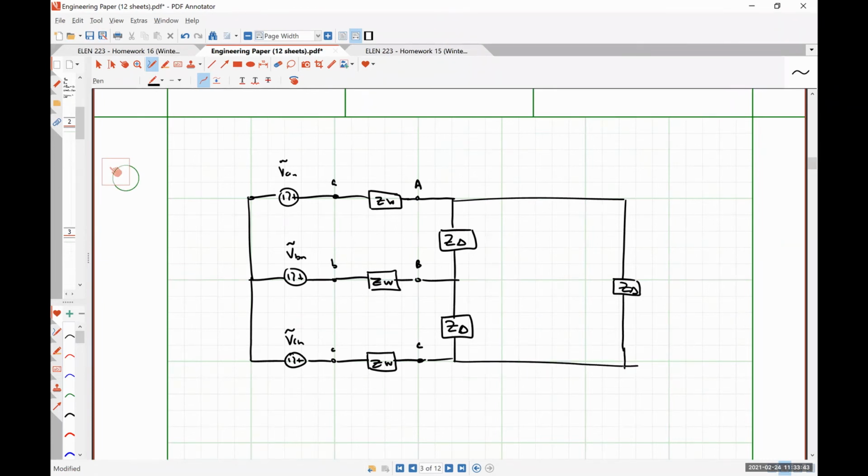And so I'm going to have phase currents flowing this way, and this way, where it's just subscript of the tail, so A to subscript of the arrow B. So I_AB, and there would also be an associated phase voltage V_AB over that portion, and I could continue on that for all the others, but I'm lazy, so I'm not going to.